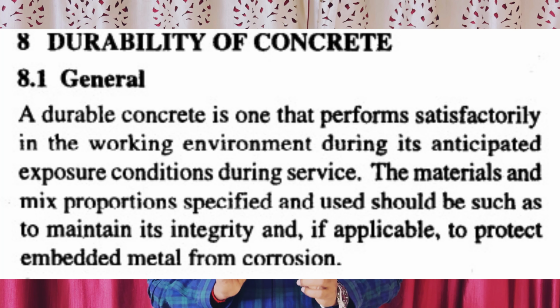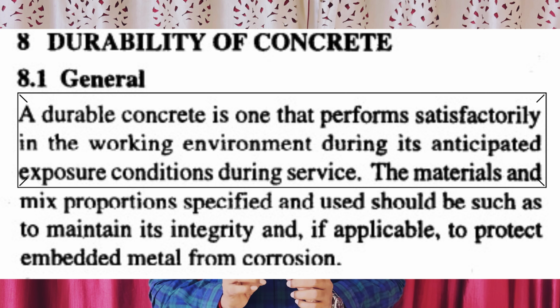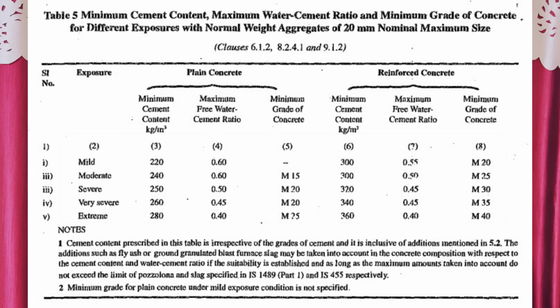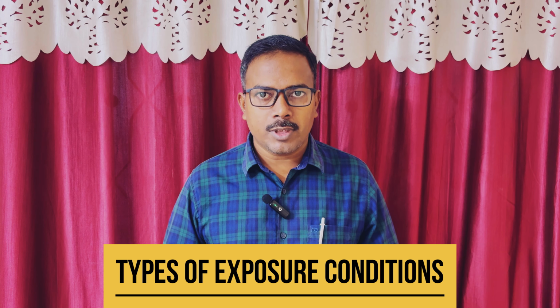Let's understand the exposure condition for concrete in an easy and simple way. If you are a civil engineer, site engineer or preparing for an interview, this video is going to be very important for you. As per IS 456, exposure condition means the environment in which concrete will remain throughout its life. It tells us how aggressive the surrounding conditions are, like rain, moisture, chemicals or seawater. Exposure condition is related to durability, not just the strength. That's why IS 456 gives different limits for water cement ratio, minimum cement content and concrete grade for different exposure conditions.